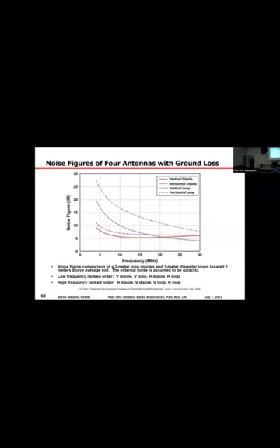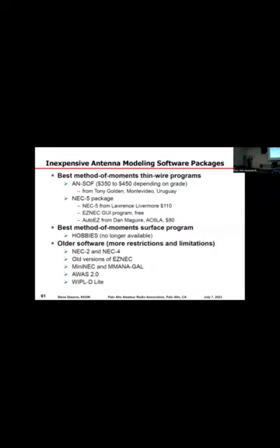Okay, next slide. Okay, what are the best software packages? Well, it used to be everybody used 4NEC2 as the GUI, which ran the NEC2 engine. But NEC2 has a lot of limitations. And it can give you wrong answers, and you won't know it.